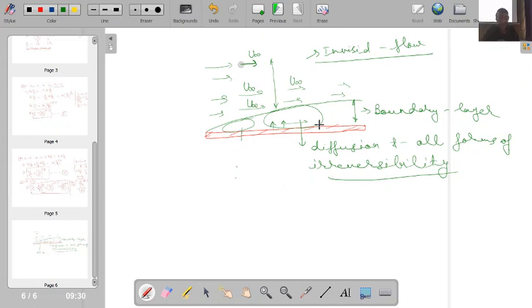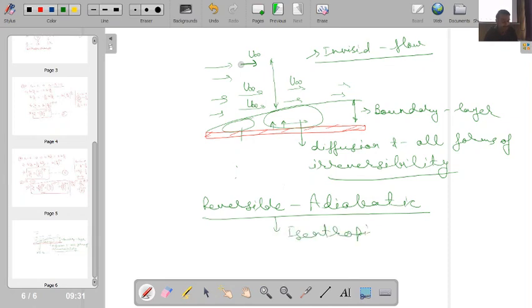and if we are not having irreversibilities, then I can say the situation is reversible. At the same point of time, the fluid velocity and the energy of the fluid will be so high that it will not have sufficient time to transfer the heat, even if some small thermal gradients are present over there. Okay, so this is the reason that for the majority of compressible flow situations, considering a reversible adiabatic situation does not introduce much error. Assuming a reversible adiabatic isentropic situation for the majority of compressible flow problems gives us accurate prediction as well as accurate analysis of the flow problems. Okay,